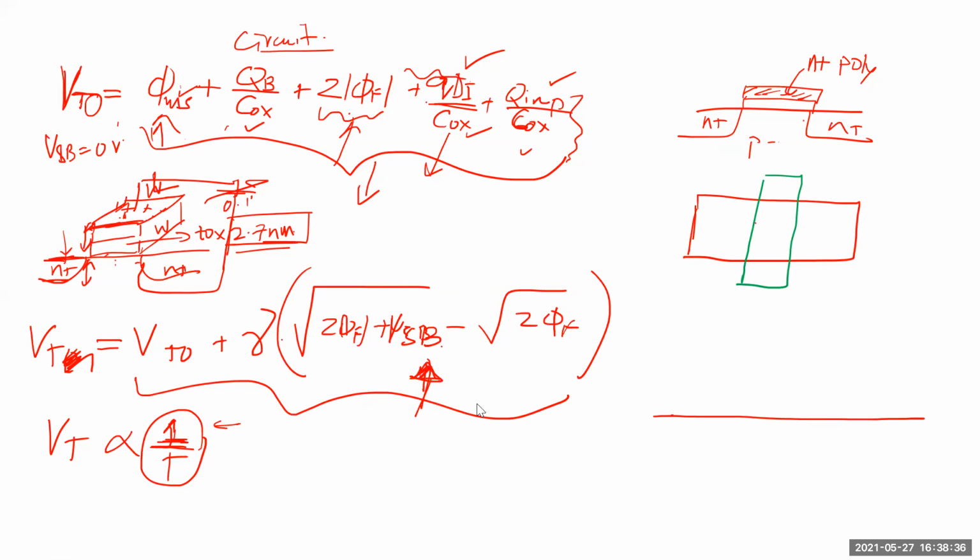You are asking whether we can change it for the PMOS. My first question was, why is it always P plus? In a CMOS process, the gate is N plus poly for NMOS and P plus poly for PMOS. That was my first question. And after you answer that, I wanted to ask you, if I change it, what will happen?